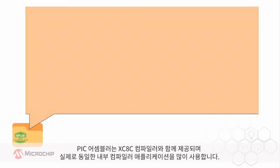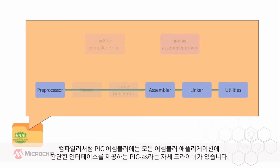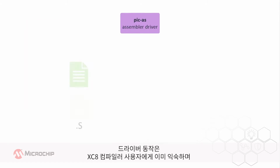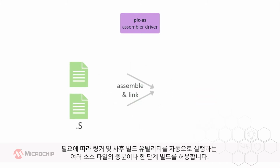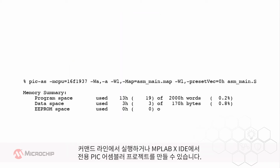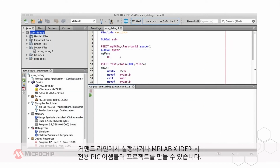The PIC assembler ships with the XC8 C compiler and, in fact, uses many of the same internal compiler applications. Like the compiler, the PIC assembler has its own driver, called PIC-AS, which provides a simple interface to all the assembler applications. The operation of the driver will be familiar to users of the XC8 compiler and permits incremental or one-step builds of multiple source files, automatically running the linker and post-build utilities as required. It can be run on the command line, or dedicated PIC assembler projects can be created in the MPLAB X IDE.